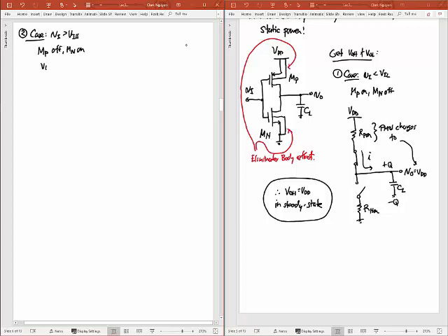And so now my circuit looks like this. I have my VDD. That's my RP on. This is going to be an open circuit. But then RN on is going to be shorted to my output, which is going to a load capacitor.